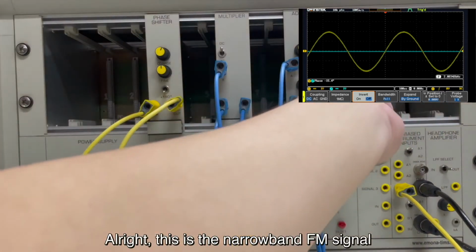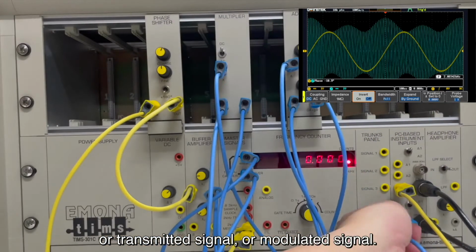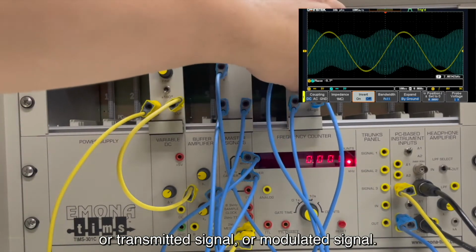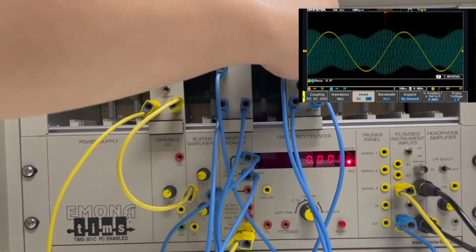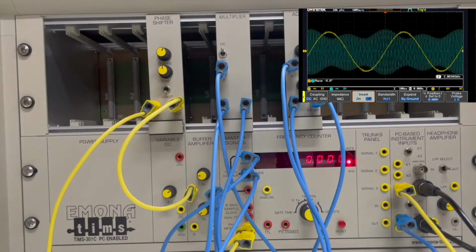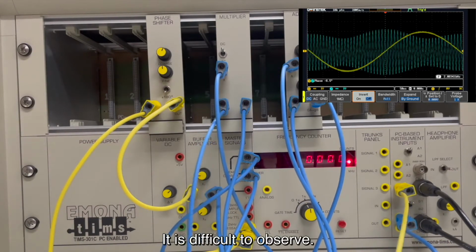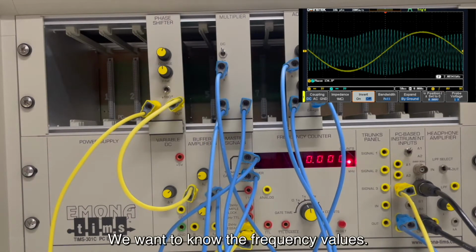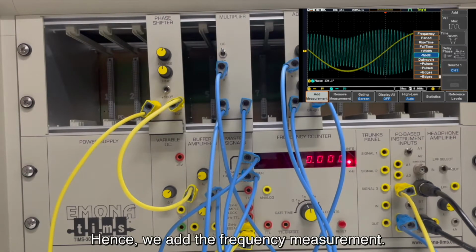Alright, this is the narrowband FM signal, or transmitted signal, or modulated signal. We display it on the oscilloscope. We get that the gain is more than 1. Therefore, we reduce the gain. It is difficult to observe. We want to know the frequency values. Hence, we add the frequency measurement.